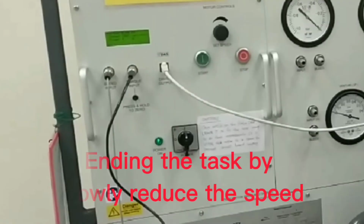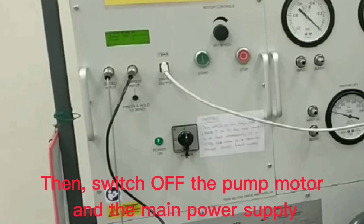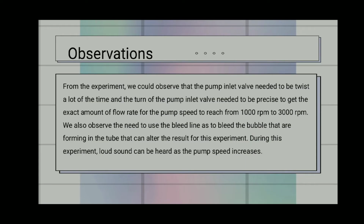To end the test, slowly reduce the speed, fully close the inlet, and switch off the pump motor and the main power supply. From the experiment, we could observe that the pump inlet valve needed to be twisted a lot of the time, and the turn of the pump inlet valve needed to be precise to get the exact amount of flow rate for the pump speed to reach from 1000 rpm to 3000 rpm.